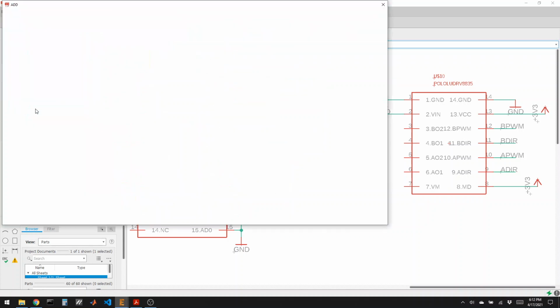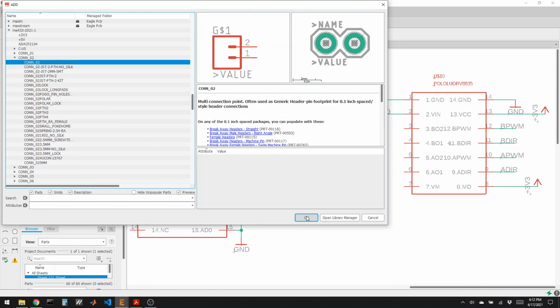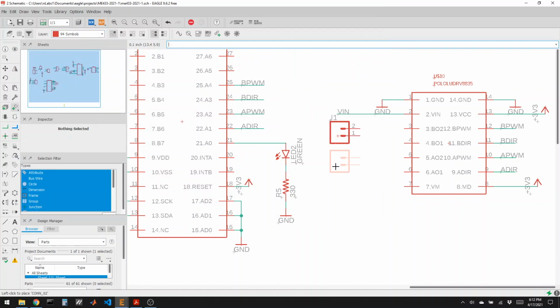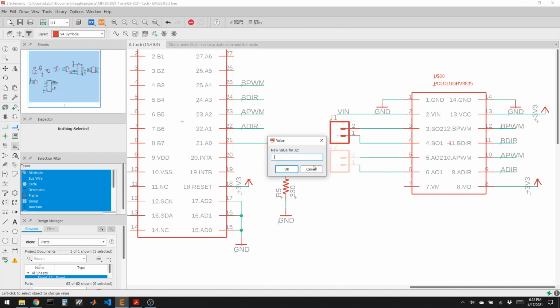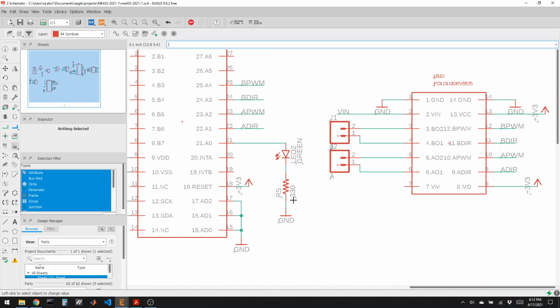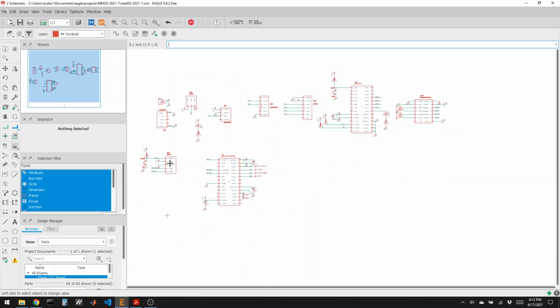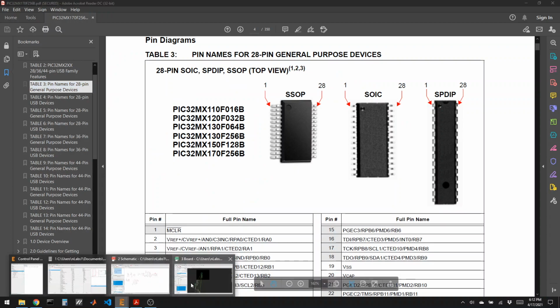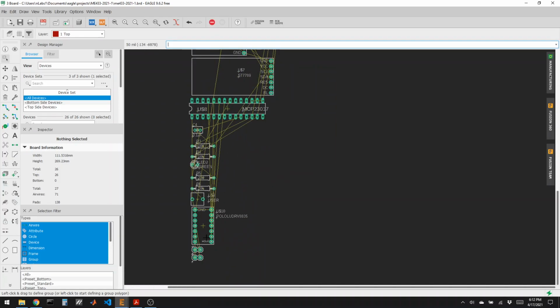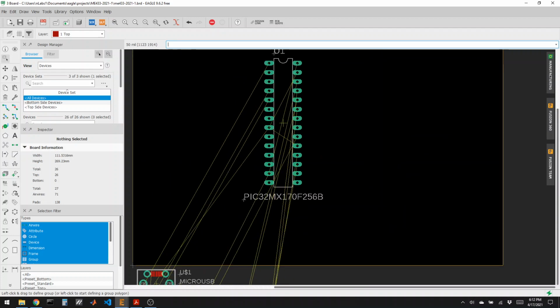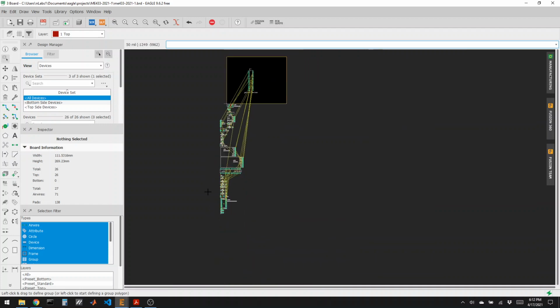And then we have to be able to plug our motors in. So we'll use two 2-pin connections, motor A and motor B. Okay, so that's our H-bridge connected to 2 motors, getting its instructions from the I/O expander and power from our slide switch. Take a peek over at all the components that we'll be organizing later on and all those wires that we'll have to make on the board layout. That'll be fun.